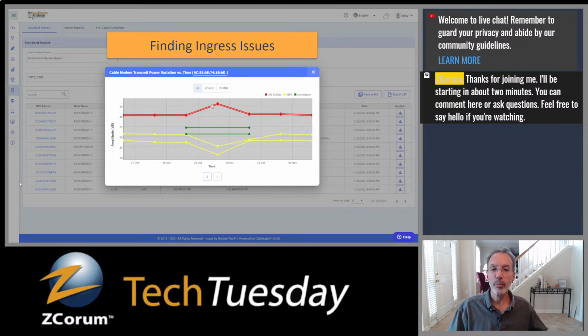So we see here, right at this point, it's very easy visually to see, and then we also mark it off with a green line that this particular device is responding. Here we've got our main tap ratio. This is the pre-EQ values changing at the same time that the cable modem transmit power is going up. And we can look back in time. You can click back here and look at another polling period, and I can see the same thing happen.